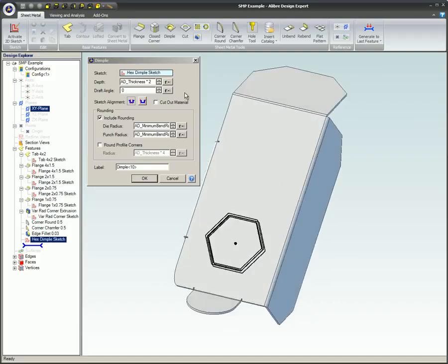When using the dimple tool, you will receive an error message if the sketch is too close to the edge of a part. The distance for the sketch to the edge is a combination of 3 times the stock thickness, K-factor, and bend radius. If the face of the round is not located entirely inside of the sheet metal part, you will receive an error message.